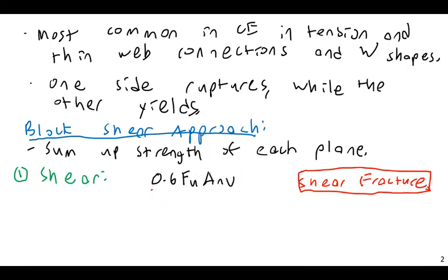And what are these things? Well, this 0.6 F_U, F sub U, again, your yield stresses, these are stresses in tension. And as we'll see later, the capacity of materials in shear can usually be considered as 60% of their capacity in tension. So to calculate the shear yield or shear ultimate stress, we simply multiply the tensile stress by 0.6.